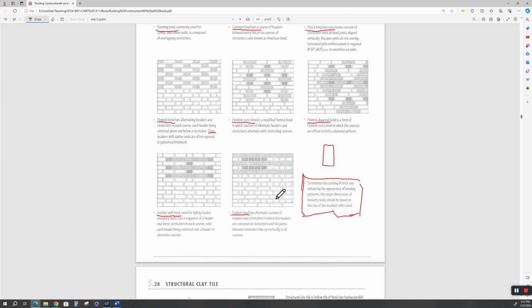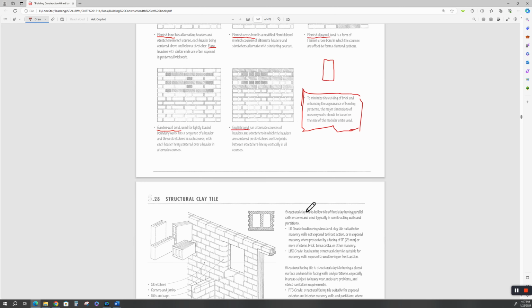And if you're mating common masonry units up, like what we would consider brick on the street and a CMU, then those are going to have to be modulared out. So you want to eliminate the number of cuttings. You can't totally eliminate the number of brick cuttings, okay, but you want to minimize it to the best that you can. All right, let's move on.